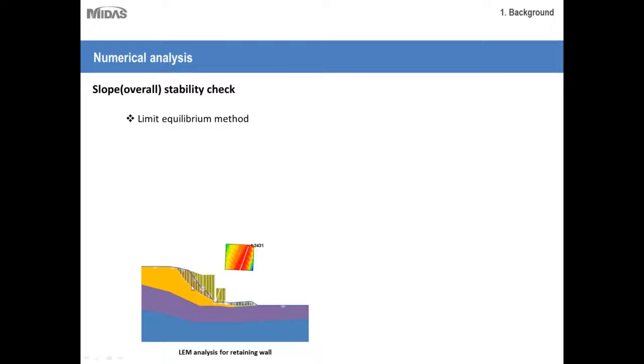They are like rectangular strips, and we define a grid set which has different radii passing through a given point, and then the program or whatever software you use would consider all the permutations and combinations to check which of the given radii has the minimum factor of safety or will be the first one to fail. So we have to define this grid in advance.